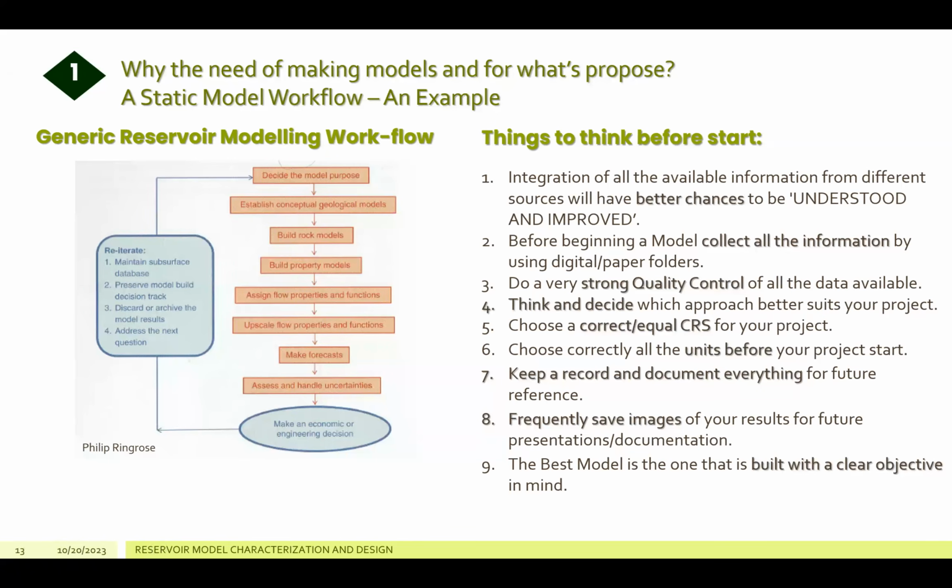Another task that is very important when you are starting a static model is the coordinate reference system, the CRS. You have to choose it, you have to read your data. Normally, the people that are acquiring the data already have some coordinate reference system. You can use that coordinate reference system and create your model with it. I'm saying this to guarantee that you have the same system as the people acquiring the data for you, that you doing the reservoir static model, and the dynamic model have the same.